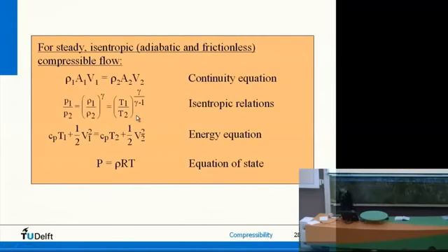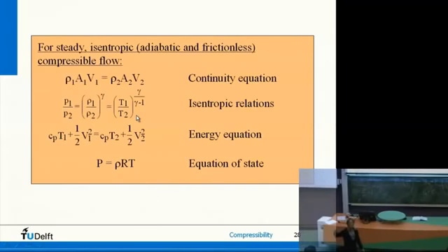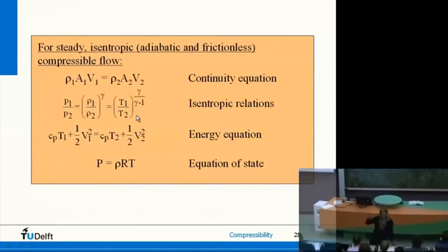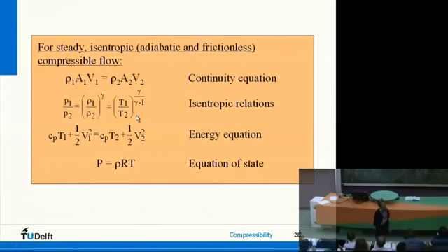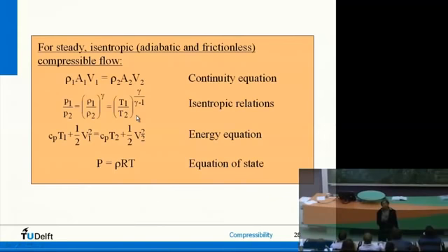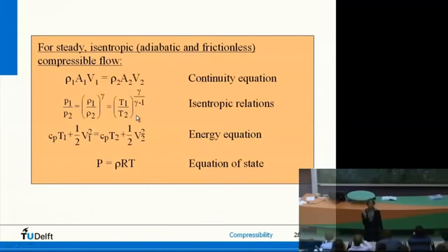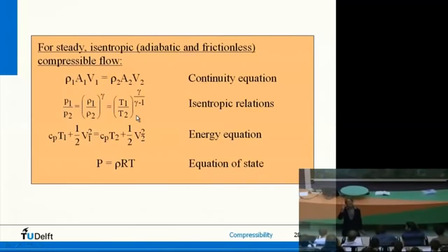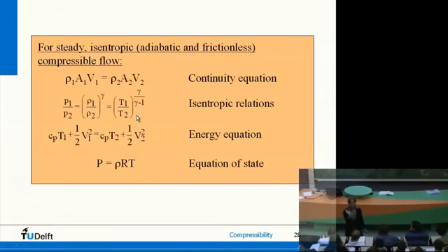Yes, question? Please, I cannot even hear the question. This equation is valid whenever it's isentropic flows, so it is valid for supersonic flows as well. Problem is, a shock is not an isentropic phenomenon. A shock, I will tell you about that next lecture, is a very sharp location with a discontinuous change of pressures, densities, temperatures, a major jump.